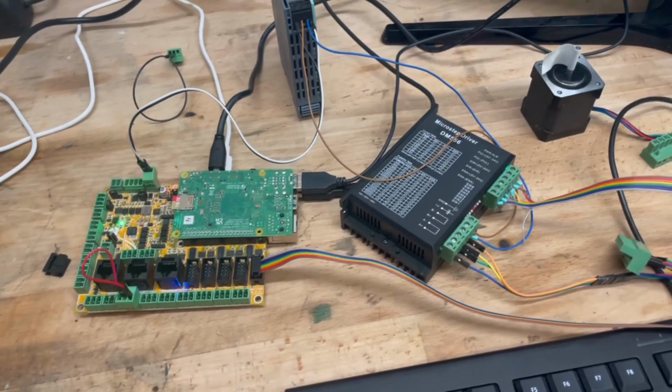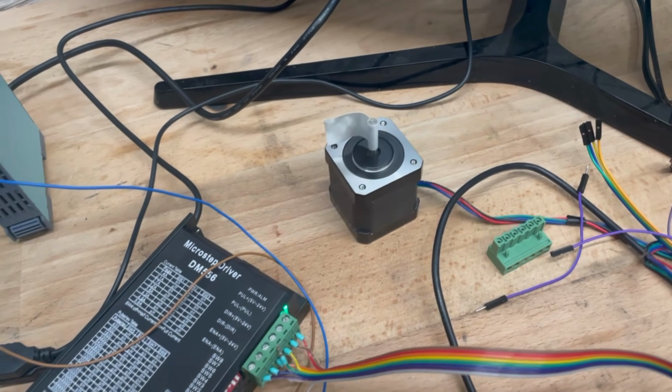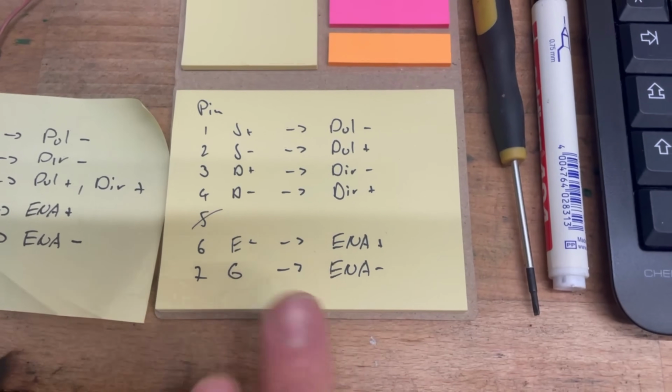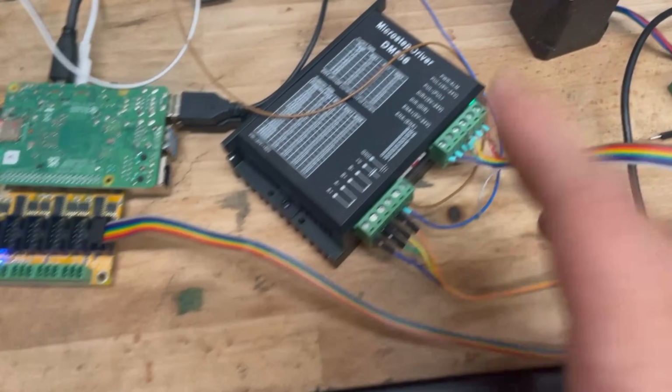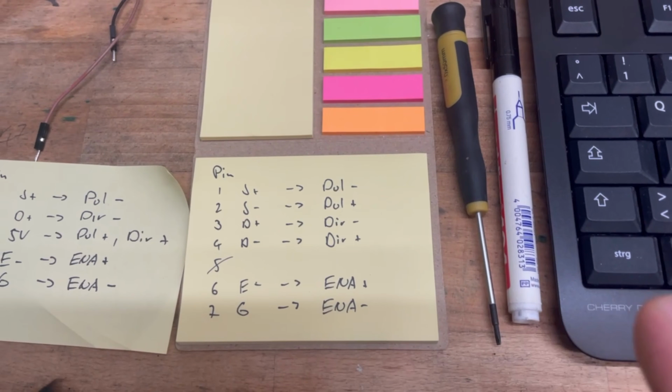After a lot more trial and error than I thought, now also the stepper motor is running. It took a bit longer because at the end I had to flip all the positive and negatives as far as I understood them going out from the Flexi-HAL to my motor controller, and that seemed sort of counterintuitive, so I tried everything else because I didn't want to break anything. Yeah, but in the end I looked at the voltages and this was the only direction that made sense.